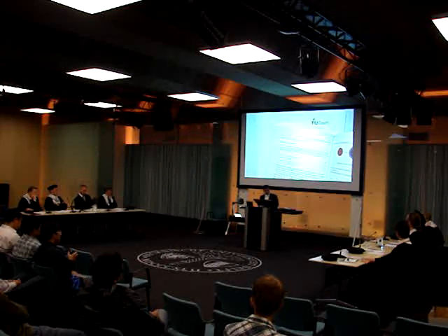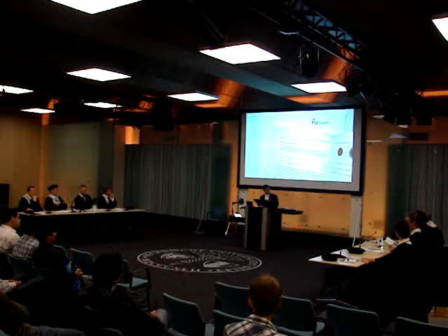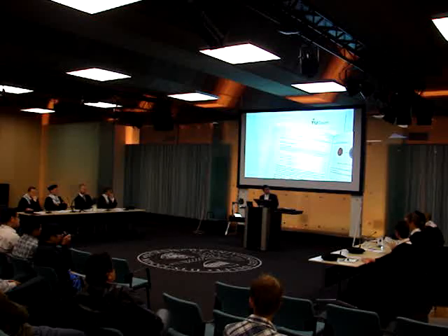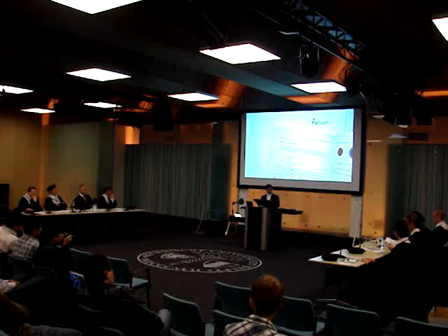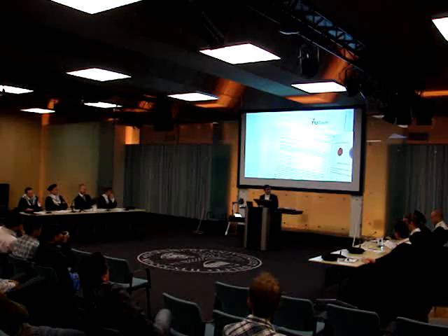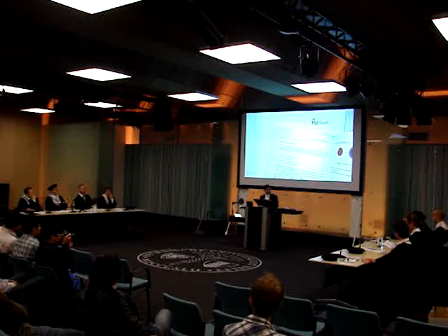Yeah. So I want to have your opinion. Or I mean, you will probably tell me you don't make everything homogeneous. You take micro properties to the macro scale. So is that true? Or do you make everything homogeneous on the micro scale and then transport it to the macro scale? Yeah, that's good. Yeah, I used homogenization to compute the effective properties of the macro sample. And the fluctuation was considered in the boundary conditions imposed on the RVE boundary. Okay, so there they are. Yeah. Yes. Okay. So thank you.